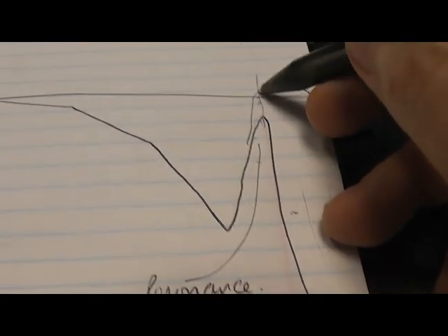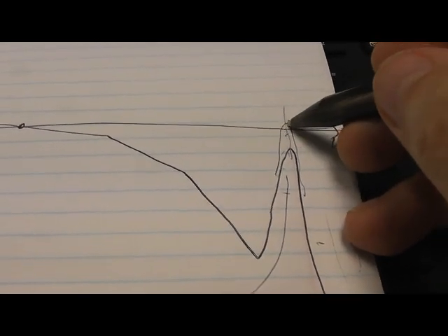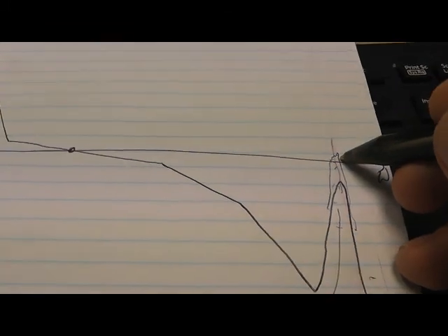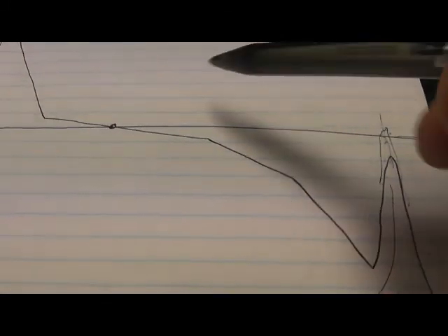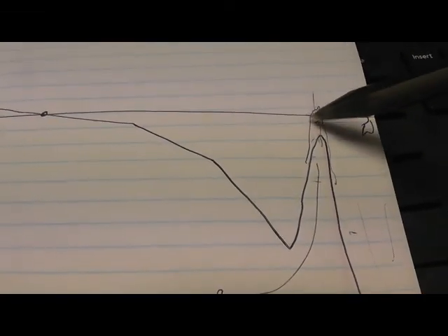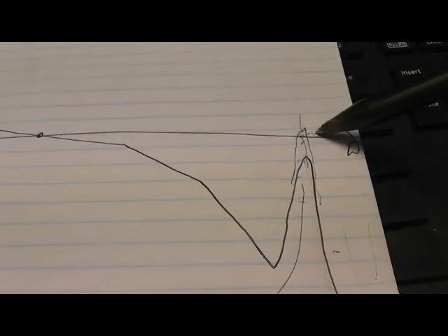Notice if you made a mistake and this was too high, what will happen is that this goes up above or through 0 dB, and you end up with another couple of zero crossings. And if you've got zero crossings, you've got phase margins. So although we've got a phase margin here, we would have two other, well, these would be very close to one another. It'd almost be like one phase margin, but we've got a couple more. We could end up with 3 phase margins. That one would be stable. This one would be unstable.